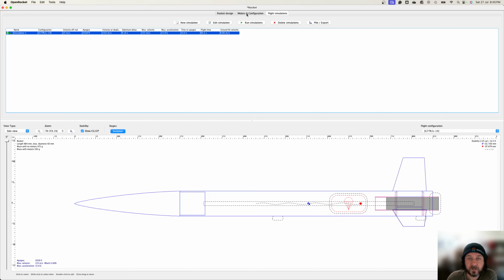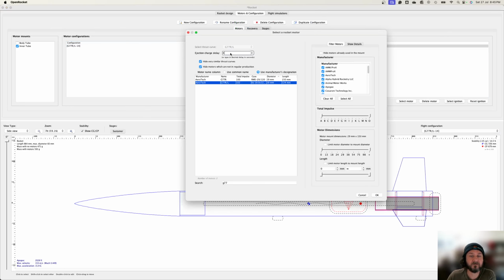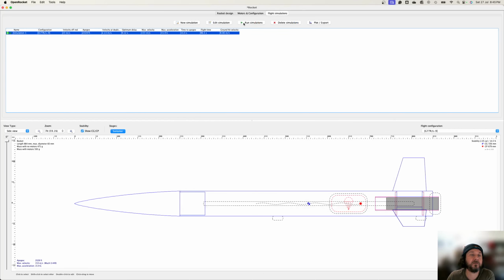So what we can do now is just go back here. We can double click on the rocket. Now that it said 9 seconds, let's just change this to a charge delay of 9, like that. It's made that 9. If we go back to simulate, we run it again, and velocity at deployment, 2.2 meters per second. You're not really going to get it any slower than that, so that is pretty good. So 9 seconds for this rocket will work.